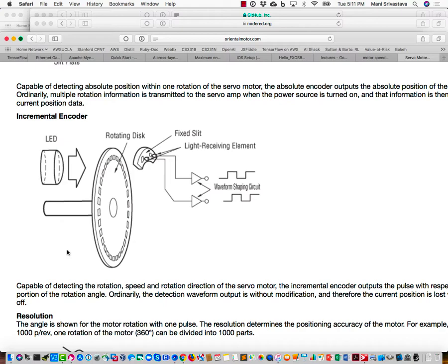Now, it's not really a real number because your resolution is going to be decided by the resolution of the timers that you're going to use to measure it, as well as what is happening to these slits out here. Okay, so there are resolution limits nevertheless, but it's a very cheap way of conveying analog information out of a motor or such devices, and sending analog information to the motor or to a light bulb.